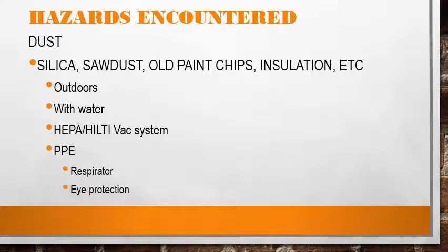If you're using a power tool that will create dust, use it outdoors or in a well-ventilated area. If you have to use it indoors, use the tool with water to knock down and collect the dust. If you can't use water, attach a HEPA vac system to capture the dust. And always make sure you're wearing the proper PPE, which would involve a respirator and eye protection.